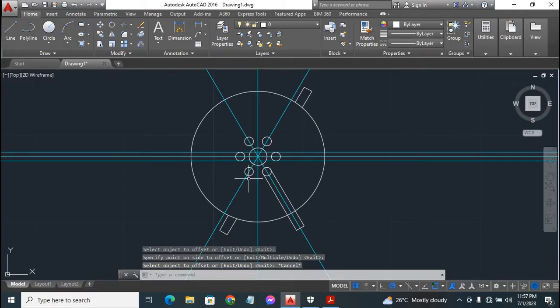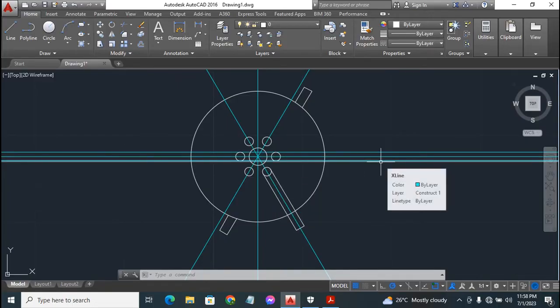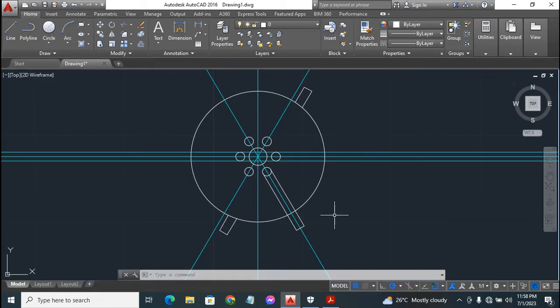So next up, we are going to draw in a tangent line that will touch the smaller circle at one point. Do the same here, touch the smaller circle at one point as well. Then we'll offset it at a distance of 8 millimeters to get the entire length of that opening. Alright, so let's do that.